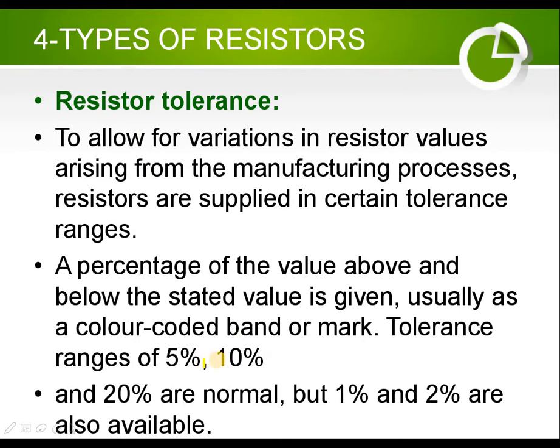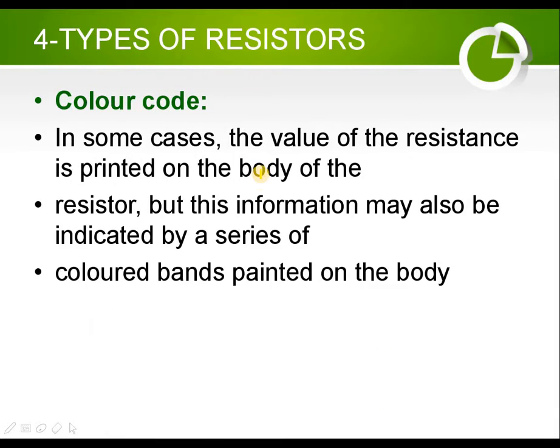Okay, if there is a 10% tolerance, it means it's not so good. For example, with 1% tolerance, it means it's much more accurate; it's just 1% fluctuation. So I always prefer the lower tolerance percentage.